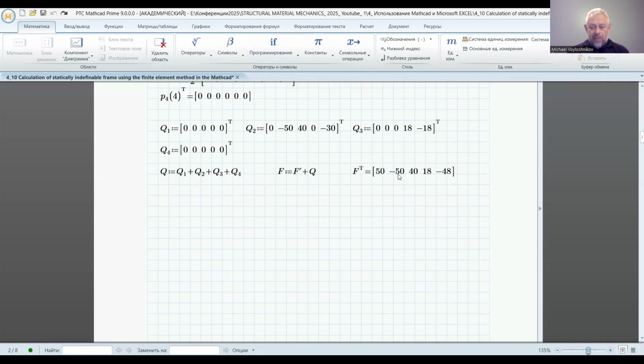We have 5 available displacements. For node 2, we have 2 translational displacements, along the x-axis and along the ordinate axis. We consider the applied load by the direction of the assigned load and the direction of the external distributed load, and the 2 directions of displacement of node number 3. So we have 2 forces, and the action of the distributed load on the second finite element and third finite element. The second is between nodes 2 and 3, and the third finite element between nodes 3 and 4.